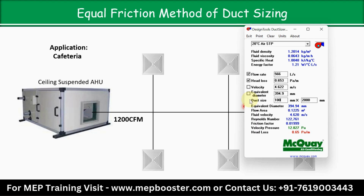Now, I have already discussed in detail that for a rectangular duct as per SMACNA, the aspect ratio is between 1:4 or 4:1. When you calculate the ratio of the longer size of the duct to the shorter size, for example, in this case width is longer than height, you can say width of duct divided by height of duct.